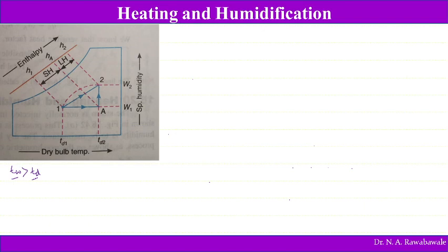Then the entering unsaturated air will reach the condition of saturation. As the air comes in contact with the hot water, the water gets evaporated, absorbing latent heat of vaporization from the water itself, thereby cooling the water.